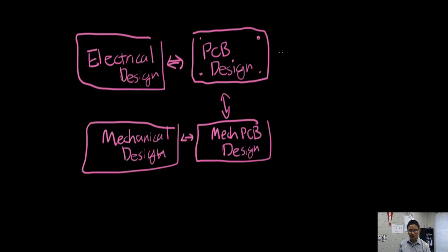So we'll talk more about that later, but once you have this iterative process where we've converged on a solution for the PCB as well as how you're going to mount it, then you get it, and hopefully you assemble and test and everything's dandy. But if not, you might have to go back and do a redesign, a respin of the board, and readjustment of the mechanicals. And so this particular aspect of hardware design is particularly interdisciplinary, and in many ways equal parts art and science, with things that you just have to pick up with practice.